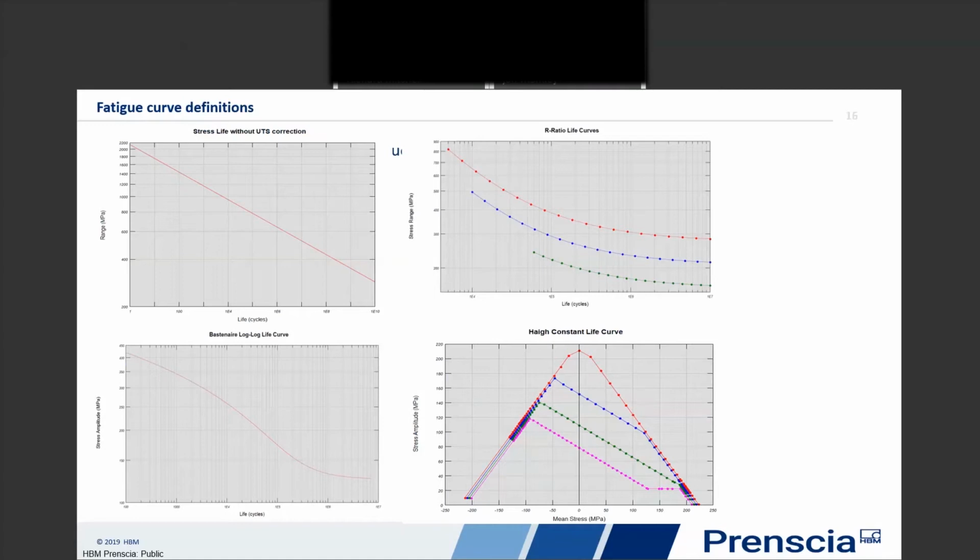And engineers like straight lines because it's easy to characterize the equation. Down below that, we have, again, a single curve, but here it's going into a relatively complex polynomial, trying to capture the low cycle and the infinite cycle regime, as well as the standard portion between 1,000 and 1,000,000 cycles.